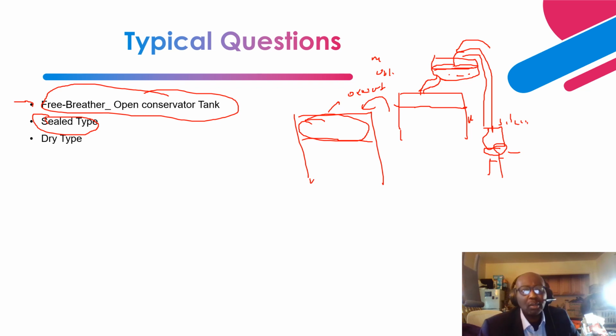And when the oil oxidates, it defeats its purpose, its function. So what they do is they put a cushion of nitrogen blanket, to create that positive pressure on top of the oil to prevent external contaminants, oxygen, and moisture from coming into contact with the oil.